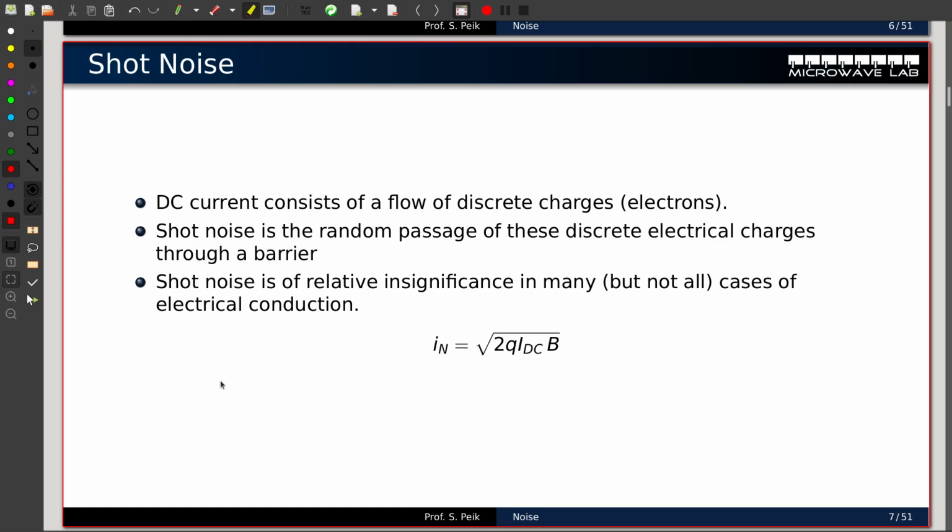Let's talk for 1 minute about the noise sources which are not of interest. The first one is the so-called shot noise. That's created due to the fact that electric charges flow through a wire in packages because they are quantized. And they are discrete packages. And since they are discrete, they do not have an extremely constant flow. The flow of electrons or charges varies a little bit due to this package nature, and we get a so-called shot noise.